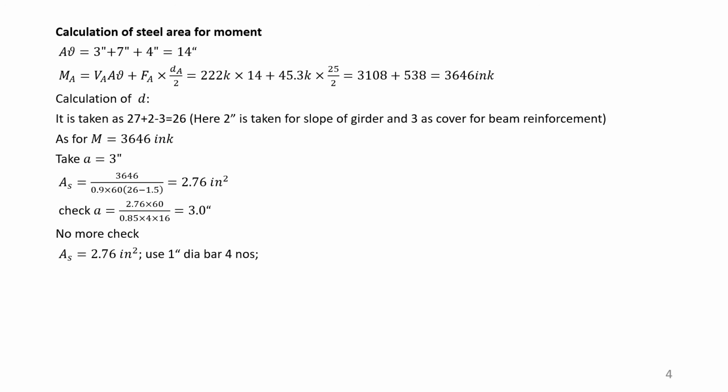The AB distance is 4, half of 8 inches. 7 is the P value, and 3 is the gap required for expansion. We have to keep a gap for expansion, and that's why this 3 is there. 3 is the expansion gap, 7 is the bearing pad edge value, and 4 is the half of the bearing pad dimension, and this gives us 14 inch.